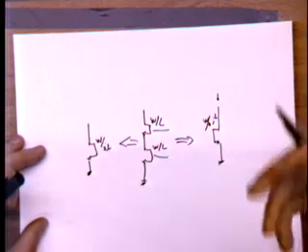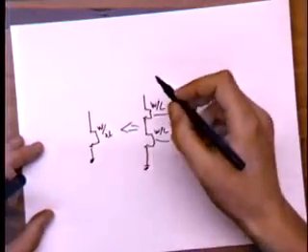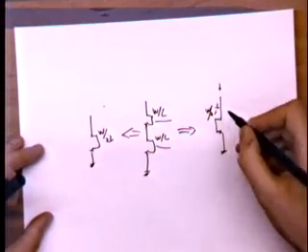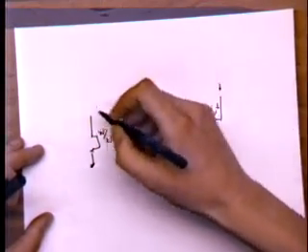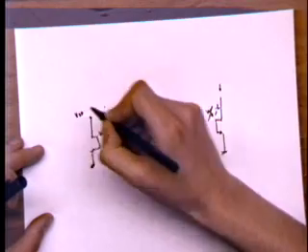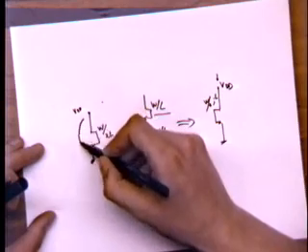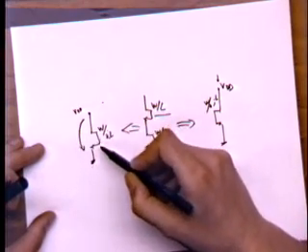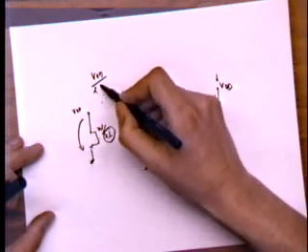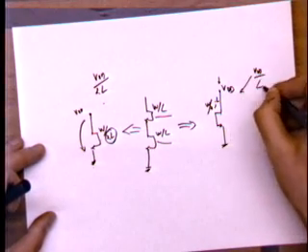But because these transistors have short channel effects, it turns out that from the point of view of on current, a transistor that has W over 2L is slightly better than a transistor that has W over 2 over L. And this is because when you are using this as a pull down, this node is at VDD, and this node is at VDD, okay? The VDS of this device is VDD. And so the average electric field, if the device has 2L, is VDD over 2L, right? Whereas in this case, the average electric field is VDD over L.